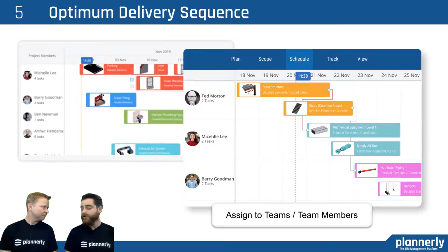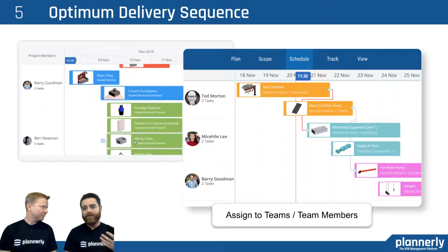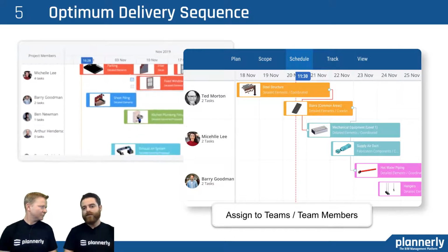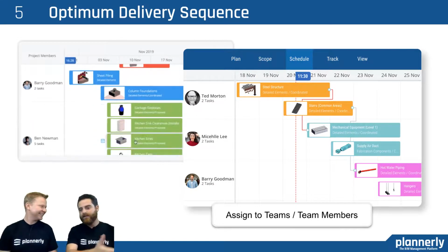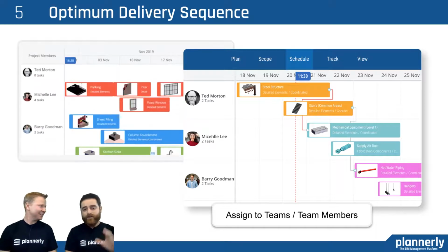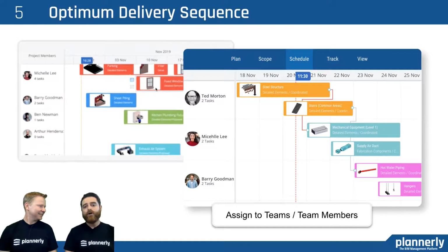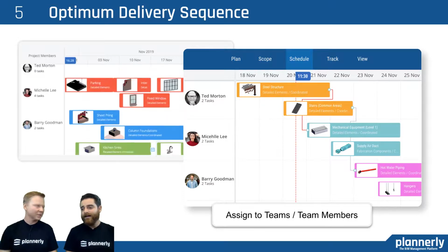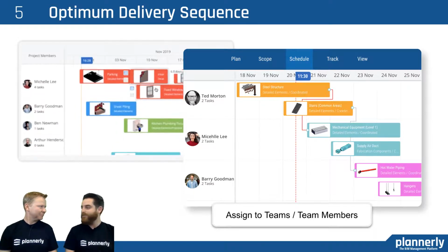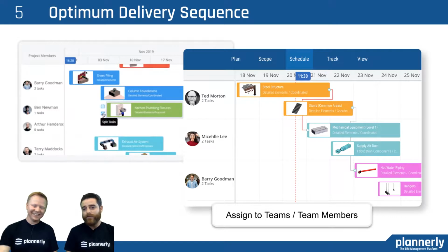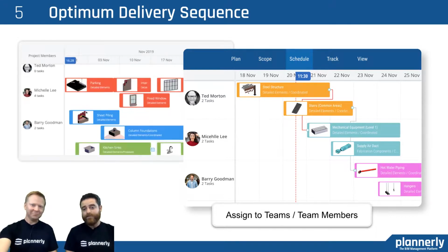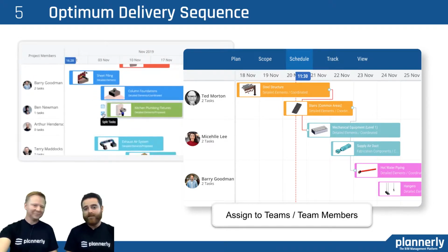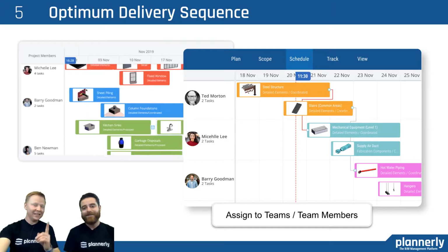Yeah, I had a subcontractor for fire protection once. We were in a meeting and we were asking, where's your model? And he said, why am I going to model everything up front when I'm going to end up having to move everything? I'm waiting for the ducting to come in, all the gravity plumbing lines to come in, and then I'll go ahead and model one time. Because his is the stuff that's under pressure that can route around other things. Other than that, I had nothing to really ask him for. He had a valid point, and I didn't really need his deliverables, his systems. Sure enough, he delivered on time still and had it all, and he did it once.